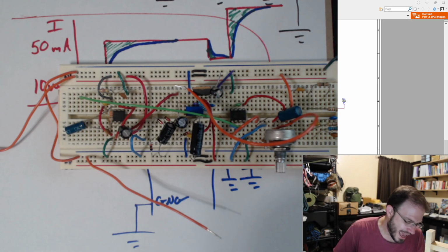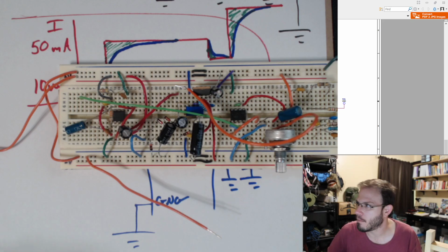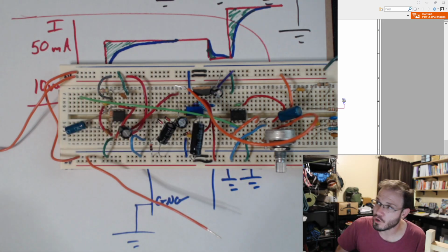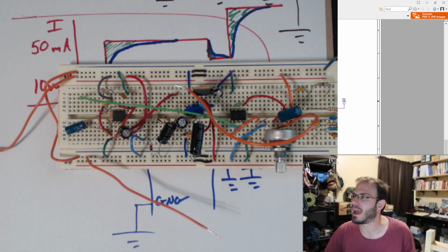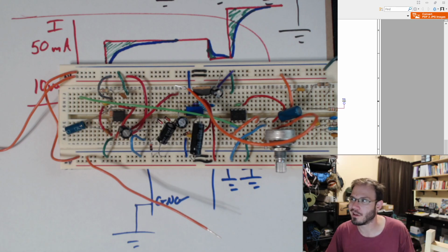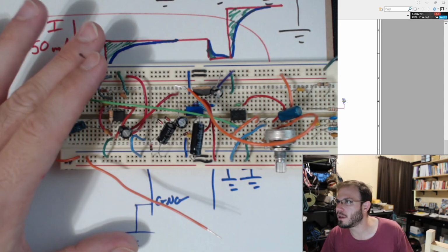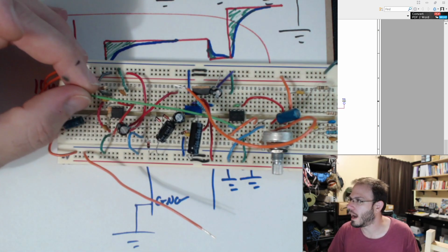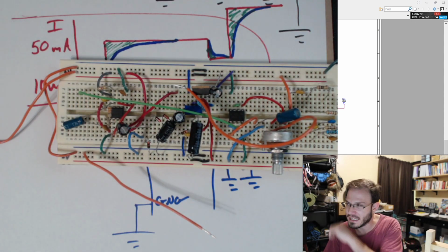So I went ahead and I added some, even though the manufacturer did not say that you should. And they gave no recommendations on that. And once I added it, all of a sudden my noise that I was looking at under my oscilloscope went down to like half of what it was before. And so then it became tolerable. And that is probably a result of having these long wires, all of them acting like inductors.